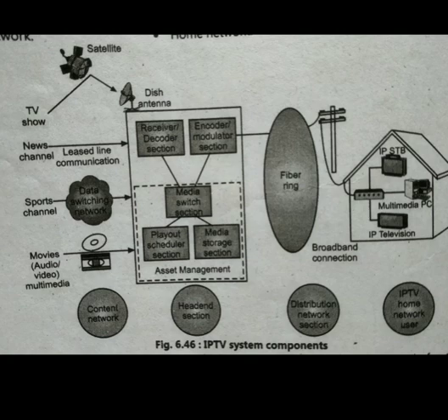The typical IPTV communication system involves the content network, then the head end, then the distribution network, then the home network; it is subdivided into these four networks and different parts of them. The first, the head end section, is a part of the IPTV communication system which selects and processes video signals for distribution into an IPTV distribution network.